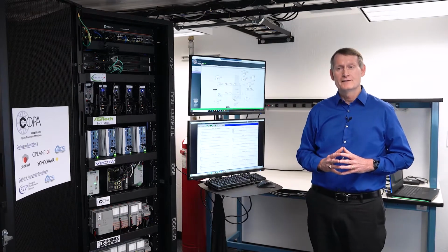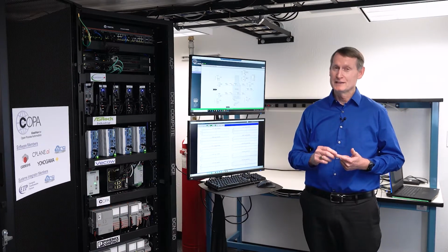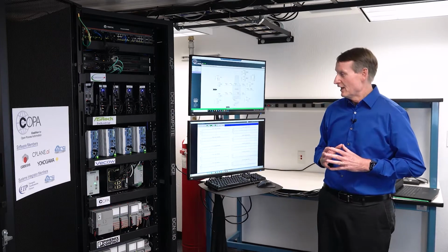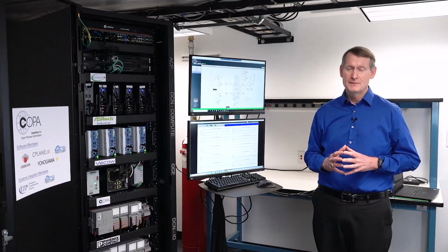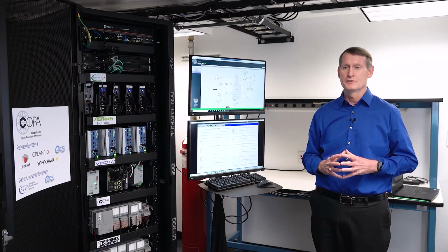Now, you may know it by a different name. There are brand names, Dynamic Matrix Control, DMC, from Aspen Tech. There's a Platform for Advanced Control and Estimation, PACE, from Yokogawa. But down under the hood, it's this same basic idea of model predictive control. Now, using DMC and PACE with current DCS systems is quite frustrating. And it's frustrating because those architectures limit what you can do with model predictive control.